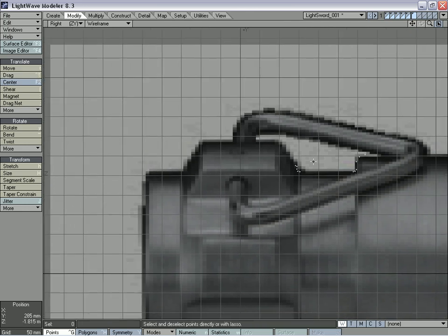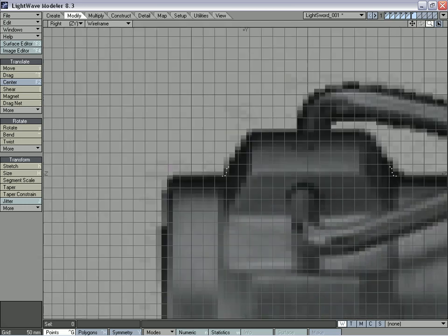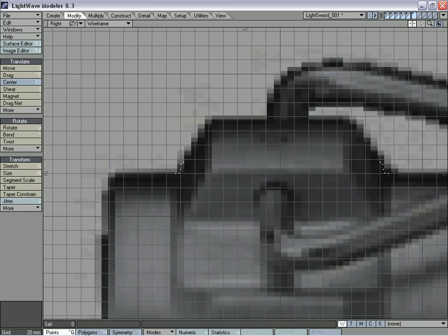What we are going to do is mirror that over, so Shift V, and that's not perfect, so select it, use the T move tool to move that into place. And actually it looks like we're raising it up a bit too much, so we're going to take these 2 points and move them down.